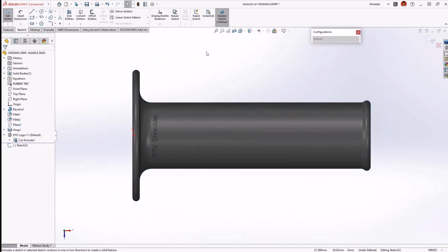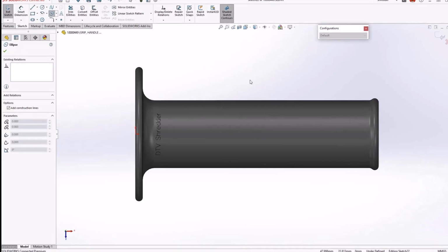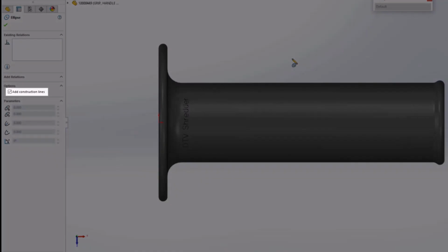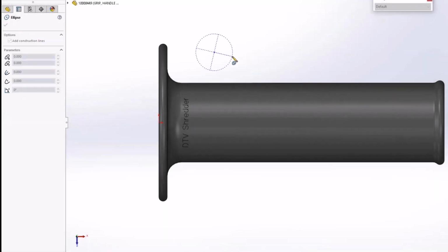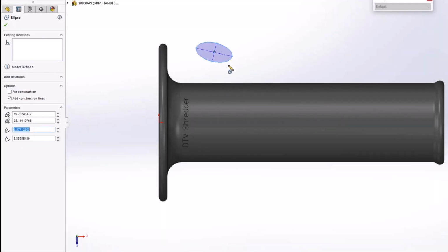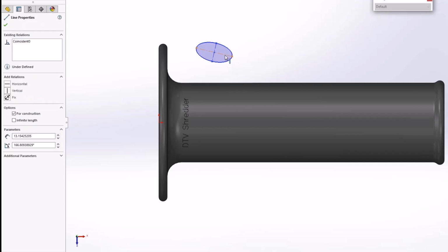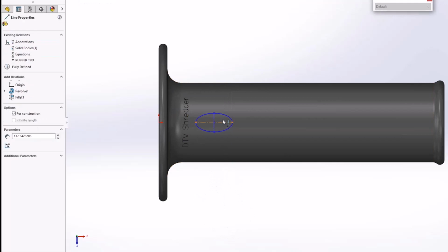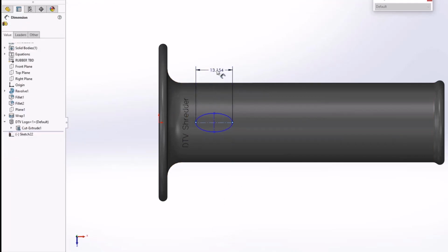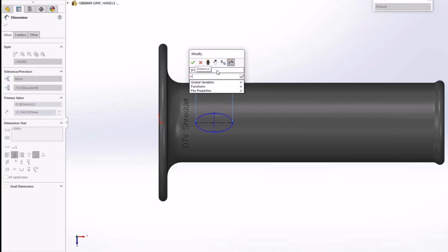Let's create a pattern of ellipse-shaped bosses to give the rider confidence when traveling over even the most extreme terrain. Beginning with SOLIDWORKS 2023, we can now create ellipses with construction geometry, making orientation effortless by selecting a construction line when choosing the appropriate relation. Fully defining the ellipse is now easier too, since we don't have to select multiple points to define the major